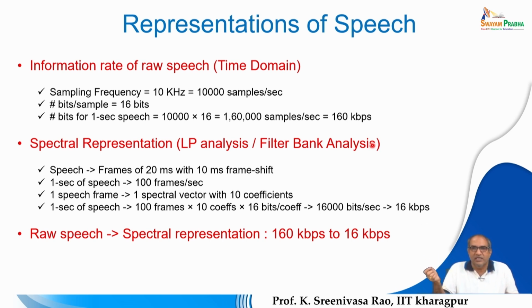In case of scalar quantization, each component of a vector is quantized separately, whereas in case of vector quantization, suppose a vector of dimension 10, all these 10 components together are treated as a single vector, and this vector is quantized altogether. Each vector is treated as one entity and quantized to some reference vector, the known or nearest or close vector. So in this topic we will discuss how vector quantization is different from scalar quantization, what its advantages are, and all those things.